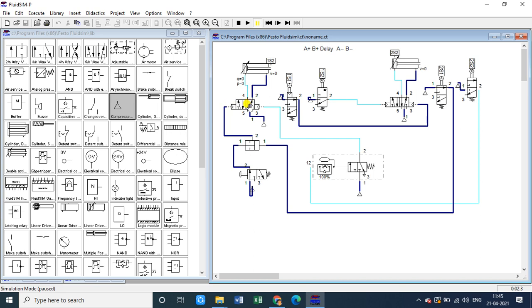Okay, now here, the air which we are supplying on the left side and on the right side, that won't go inside the cylinder. Okay, now which air will go inside the cylinder, that we are supplying at port number 1 to this air service unit. Here the air service unit is connected, that is what this means. This is the icon you can see here, compressed air supply.